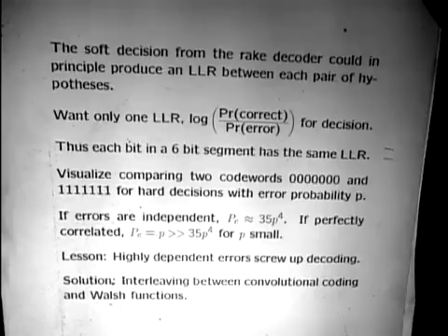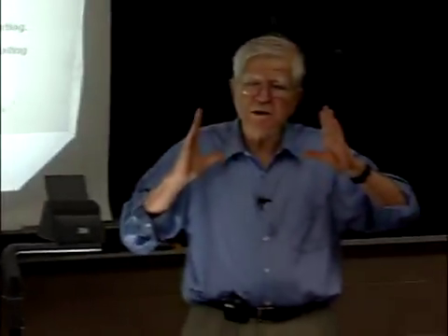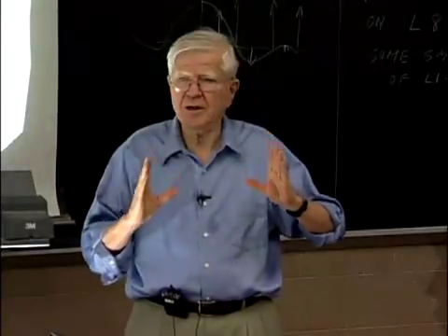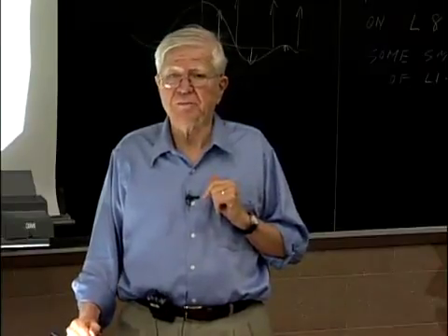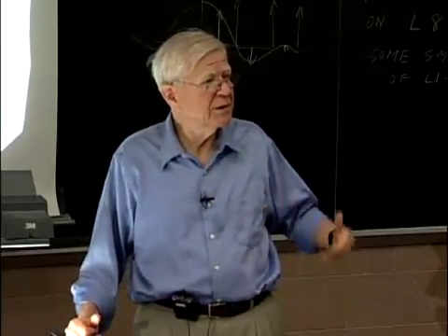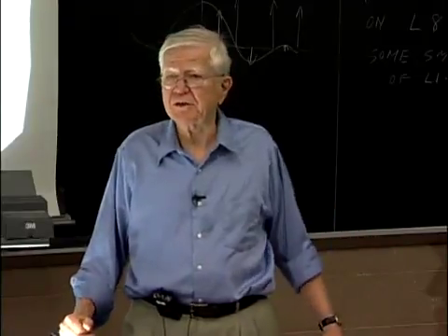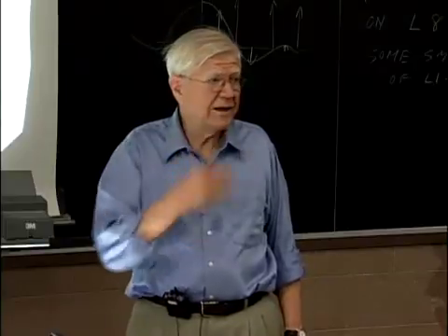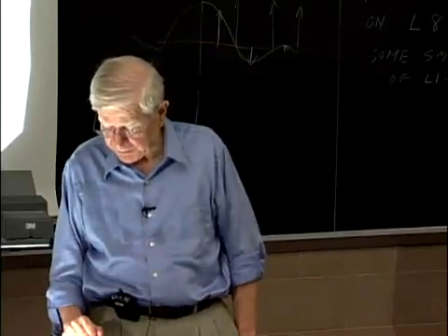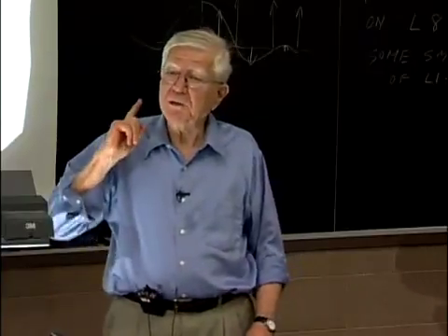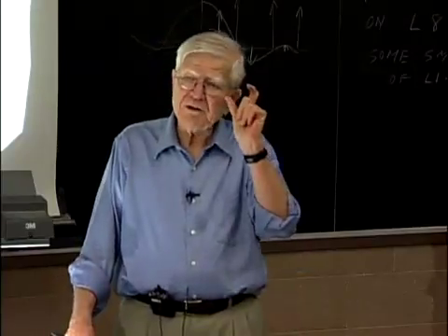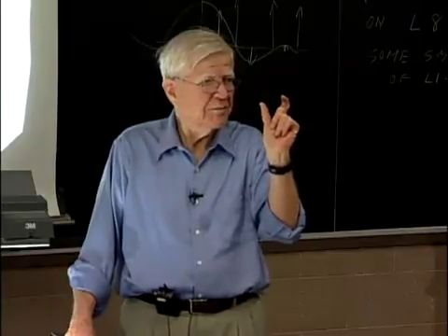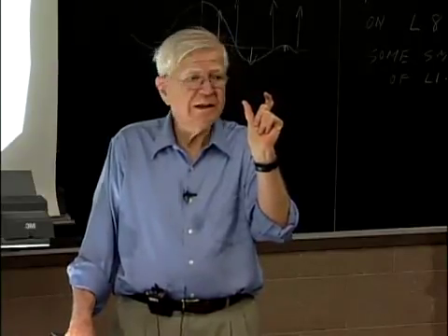And the Viterbi decoder, since it's operating on these states, it can actually deal with these log likelihood ratios as well as anything else. That's one of the reasons you want to use a Viterbi decoder, because most coding devices that people have invented don't work very well with analog signals. This does work well with analog signals. But the problem is, anytime you make a mistake on the 64 orthogonal waveforms, you have a 6-bit block of digits, and you're going to be wrong typically in 3 of them.